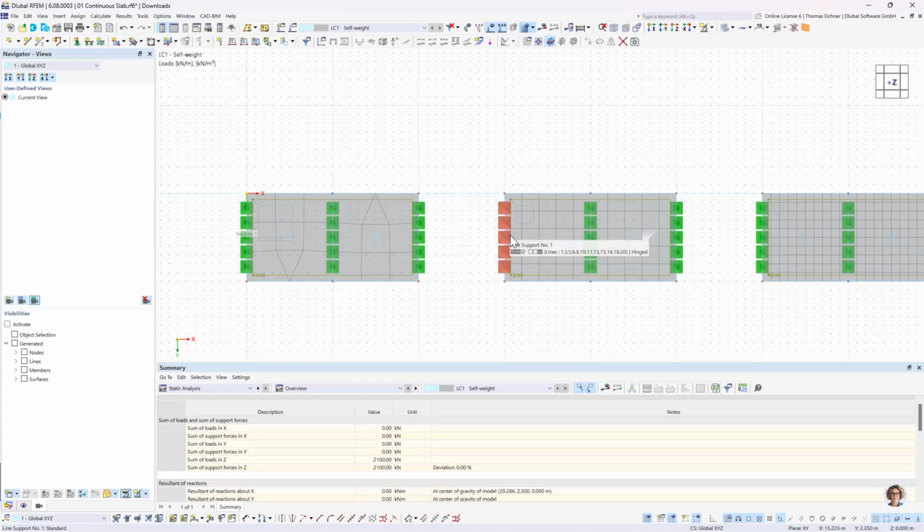You should use 6 elements between 2 supports, or also if you have a line load or a support load, you should also have 6 elements between this line load and the next support or line load. Like everything, if there's a change in the boundary conditions or the force, there should be around 6 elements to the next change.